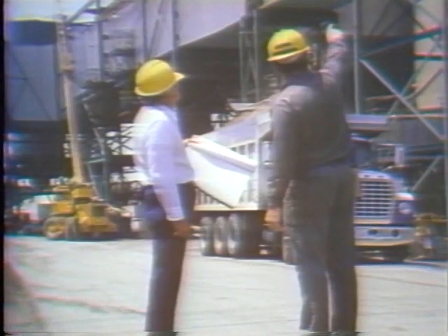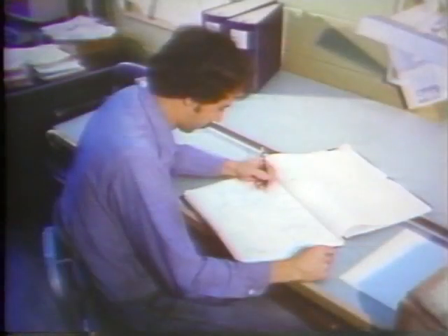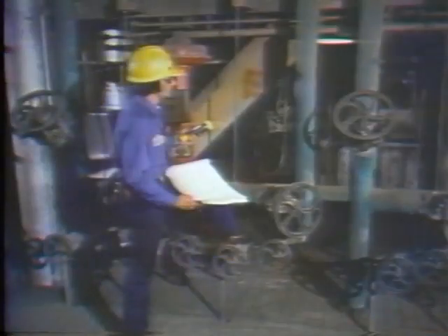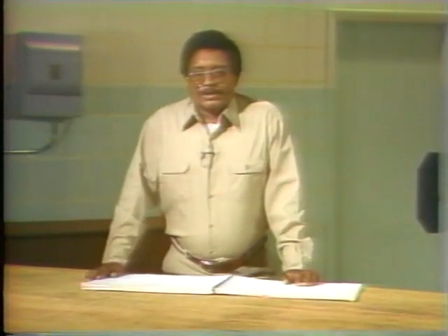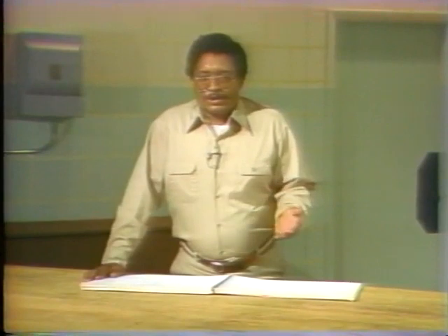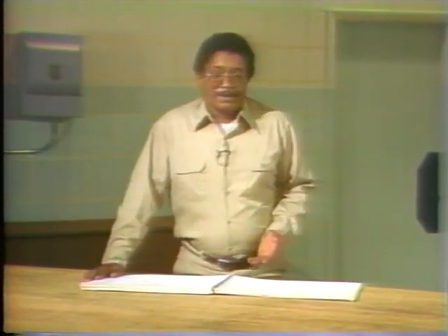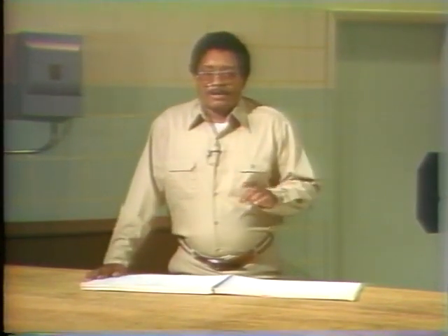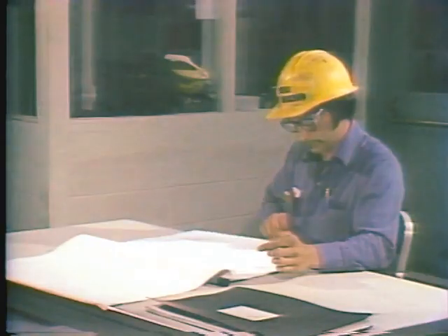Let's begin by covering some of the most common uses of P&IDs. Initially, they're used by people who build the plant. They're also used by engineers to evaluate the operation of systems and to make modifications when necessary. As an operator, you'll use them to trace systems and to find out how each system is laid out, as well as where components are located. P&IDs also tell you what instrumentation is installed for each system and where it's located, and you'll find P&IDs a valuable tool for daily operation.